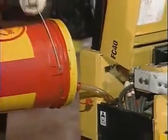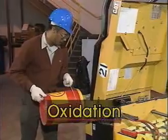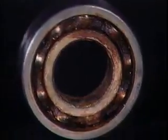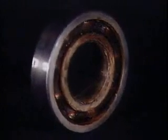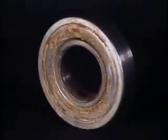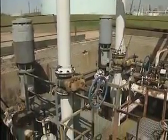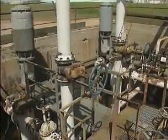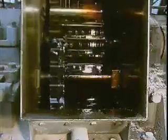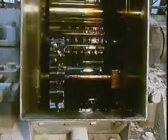You see, many industrial lubricants are made from hydrocarbons. When the hydrocarbons are exposed to heat and air, the chemical reaction called oxidation occurs. Oxidation causes chemical changes that destroy a lubricant's effectiveness and lead to the creation of deposits such as sludge and varnish. Oxidation also produces acids that cause rust and corrosion. The oxidation process is normally slow, and over time, most lubricants do tend to oxidize. Oxidation can speed up, however, if the lubricant splashes around excessively or if it's exposed to high temperatures.